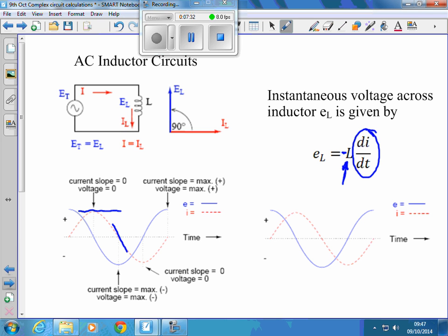Because what happens is the impedance that you get for an inductor is because the voltage generated across it opposes the current that's causing it to happen. So it becomes a reactance, and it's frequency dependent as well, because the faster we make the change, the more voltage we get. So we're now not a simple quantity, we've got a complex quantity.